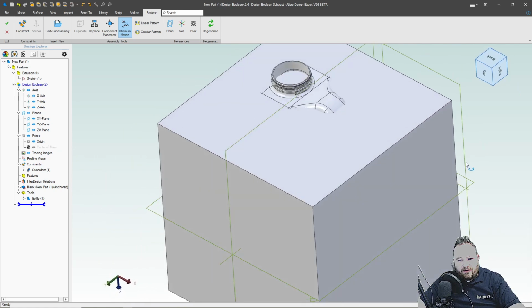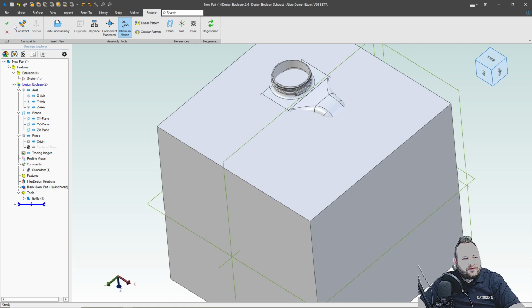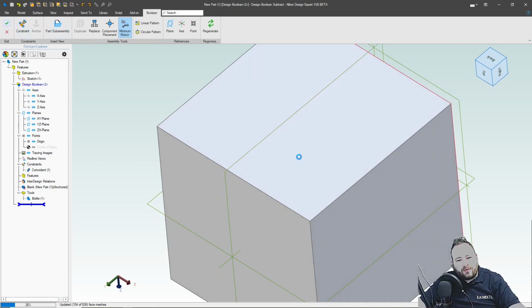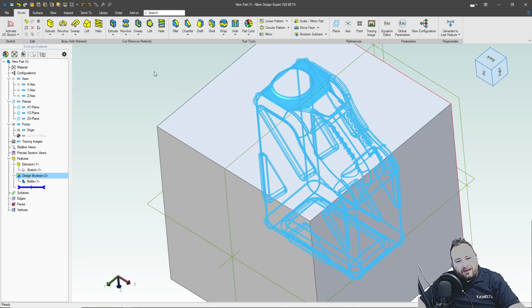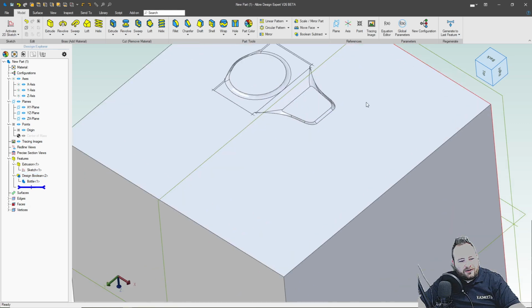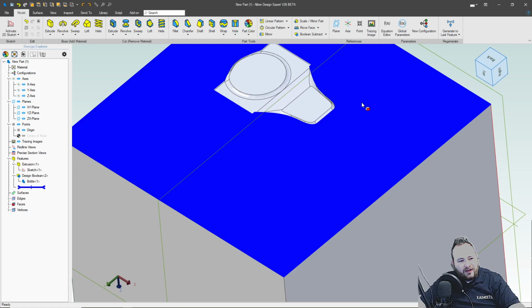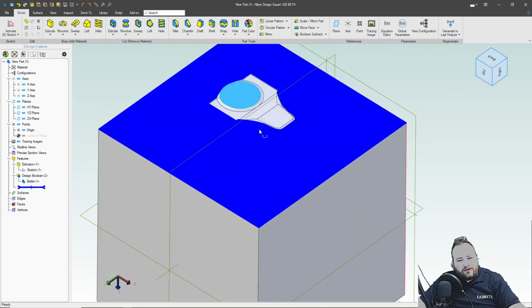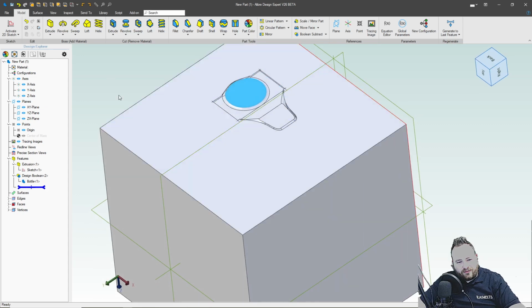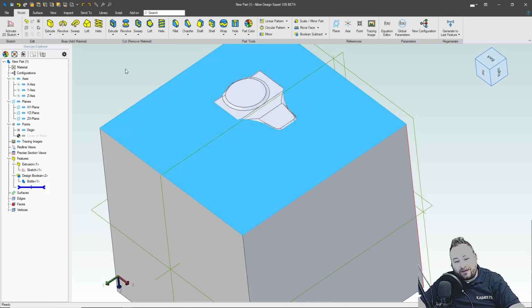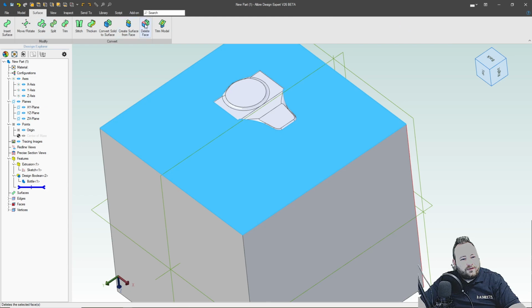So we're going to hit the green check, and we're subtracting the bottle from the cube. And now this cube is actually in two different solid bodies, right? We have kind of this internal body and this external body. Obviously, if I take the volume of this, it's not going to be the volume of the fluid. So, because we just found that the volume of a surface is 0, why don't we just come over here to surfaces? We'll delete face.